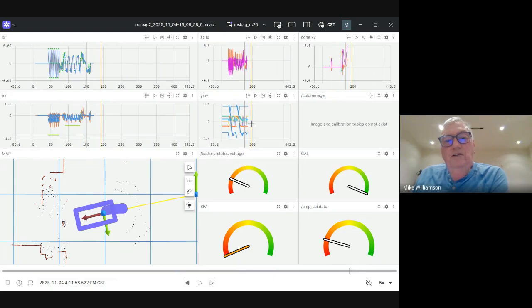Using a ROS bag, I can inspect it and make sure all the sensor values are as I expect. I can't wait to bring it outside where my satellite's in view. About right here is like 10 satellites, which is where it starts to work well. When it's below 6 satellites, I just block the GPS data because it's completely unreliable.